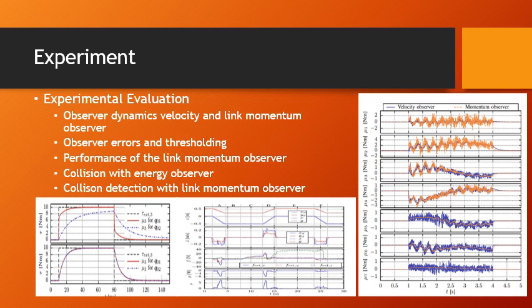In this scenario on the right, we see external joint torque estimation in all 7 joints with sinusoidal motion for tau external, under ideal conditions for t greater than 1 and less than 4. In the first image of the plot, we can see the external joint torque and its estimation for the velocity observer and the momentum observer at the initial configurations of the robot.